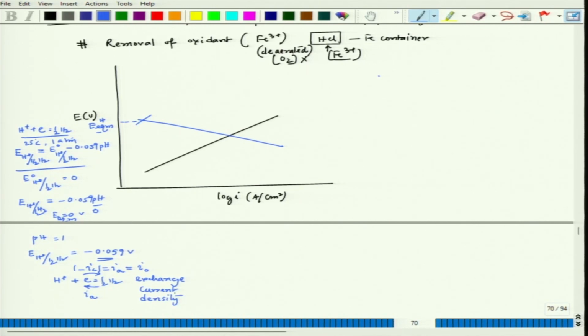Fine. So, now when we achieve this equilibrium, at that time there is no net gain of hydrogen gas or no net gain of H plus ion. So, that is basically a non-corroding situation. Non-corroding means... corrosion is a constant loss of metal, but here why are we saying non-corroding? Because there is no net change of hydrogen ion or H2 gas or H2 molecule. Okay, so that's what it is, a non-corroding condition, and it also corresponds to equilibrium.